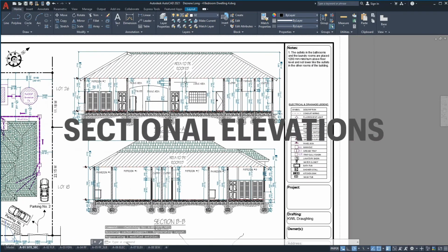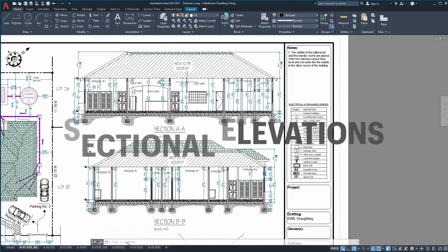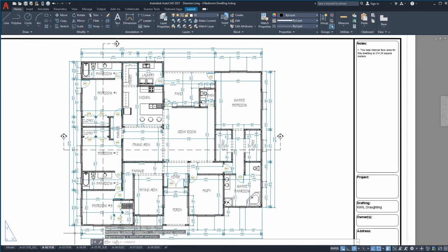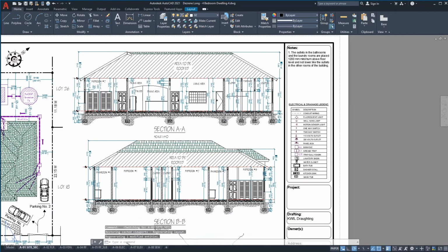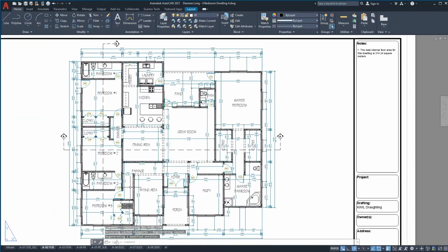Now this is an elevation, but it's a section of the building, meaning you're cutting through a section of the building, and this section that you're cutting through is showing the cutting plane line. So this is the point that you slice the building, and you're looking upwards from this view, but you're looking in the building from a frontal view, and this is from the side view, and this cutting plane line from the side view is shown here. Some more details on that when we get to that stage. So that is what the sectional